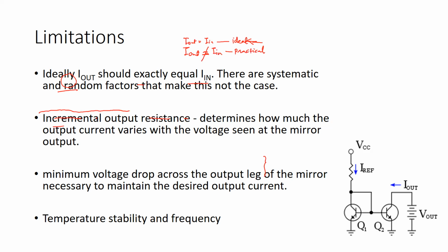And when we say a saturation region, you make sure that your base-emitter junction is forward biased, and this junction is also forward biased, right here. If the collector-base junction is not forward biased, then your transistor comes out of saturation. It may enter the linear region. So how will we see that in the graph?